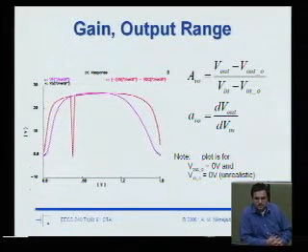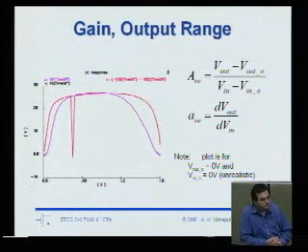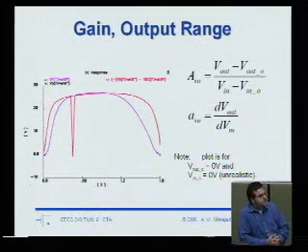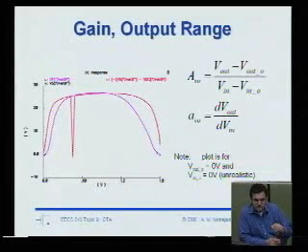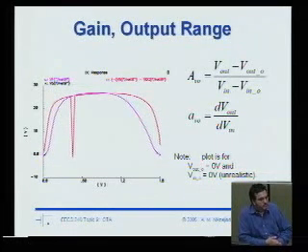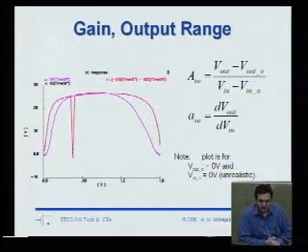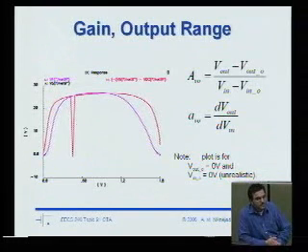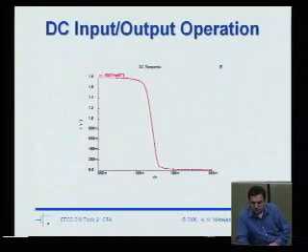So why is it I care about the large signal gain? Let me give you a hint. Think about the applications that we're thinking about. We're going to use this as a gain block in some switch capacitor circuits. Well, let's go back to small signal gain. Why? What the hell is small signal gain, right? Small signal gain is the gain you get when you apply an infinitesimally small signal at a given operating point. So if I'm, let's say, at this input operating point and I apply a very, very tiny signal, then the slope I get here is the gain, right?